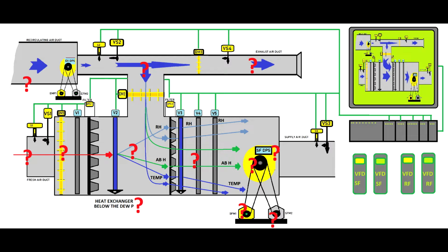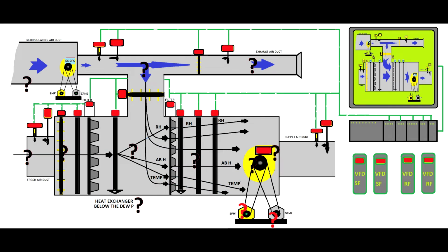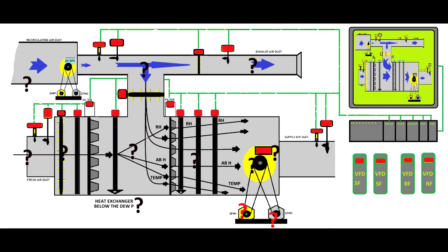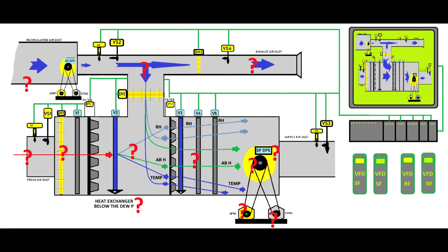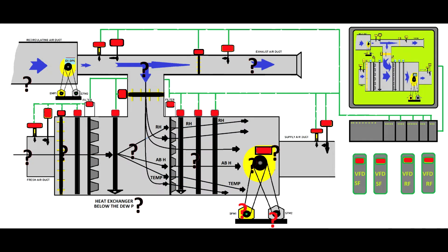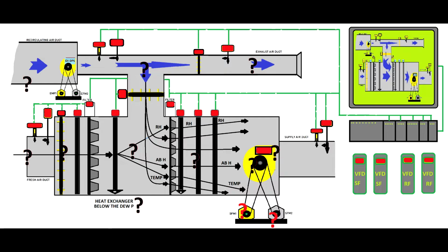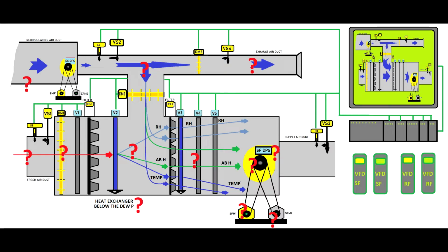We also have on the right hand side to the bottom the variable speed drives, which get instructions from the programmable logic controller. So by looking into this video, you'll observe how many things you have to consider when you design an air handling unit. You have the actuators which are controlling the valve that allows the glycol or the heating agent to pass through a heat exchanger, so we can control the air temperature and humidity.